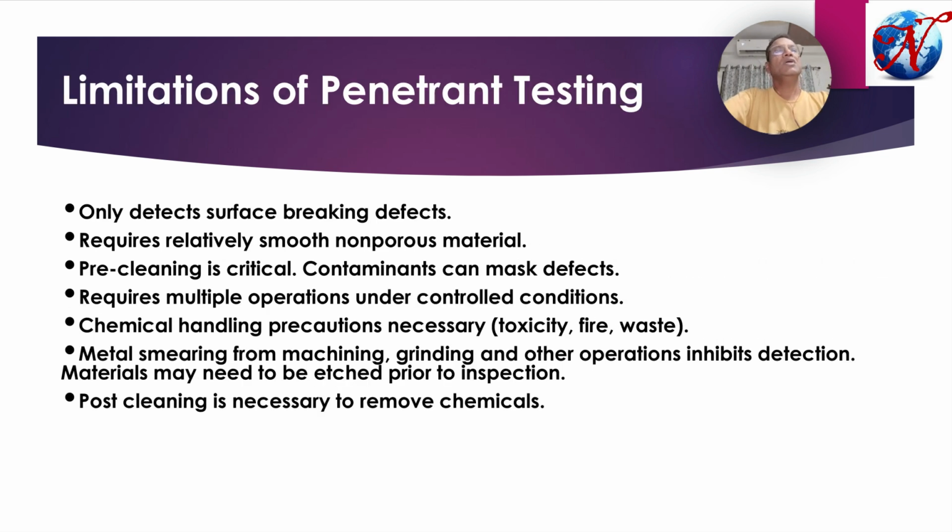The limitation of liquid penetrant testing is that only materials which are non-porous in nature, and defects which are open to the surface, can be identified. If geometrical abnormalities or a critical job geometry are there, there is a possibility of excessive background, and in that scenario it is difficult to inspect in a correct way.